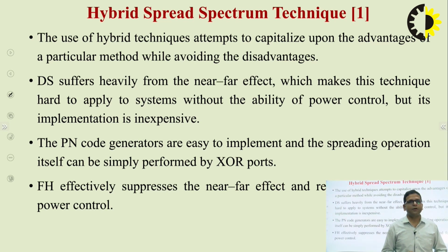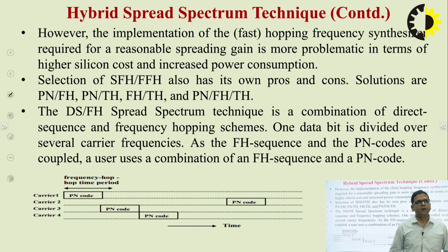So some kind of power control must be provided to avoid this near-far effect, and this provision makes the system more complex and expensive. So, in many applications, we integrate the direct sequence spread spectrum technique with the frequency hop spread spectrum technique to fulfill our desired applications.